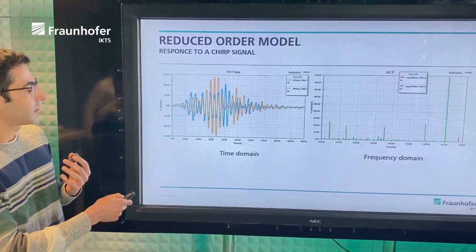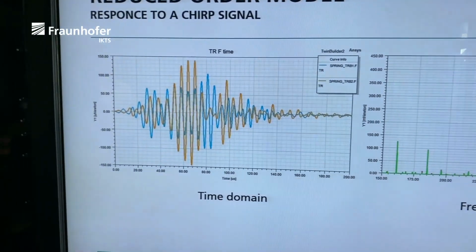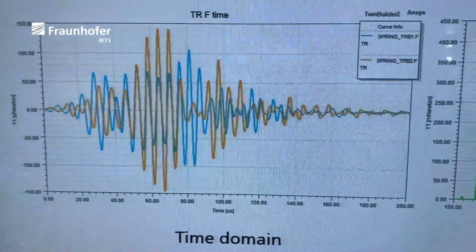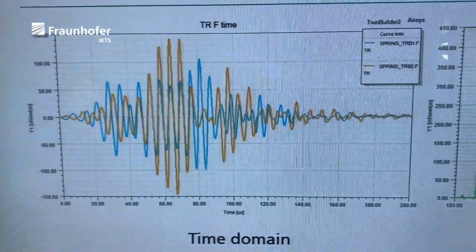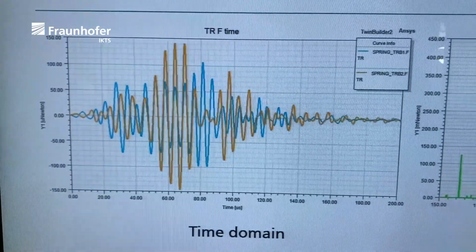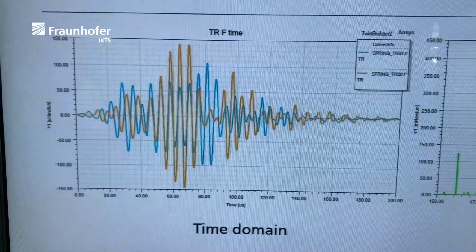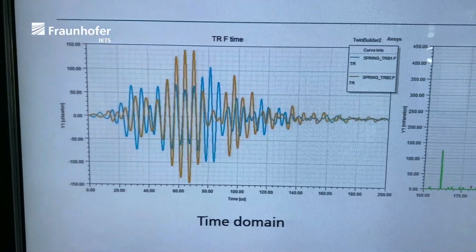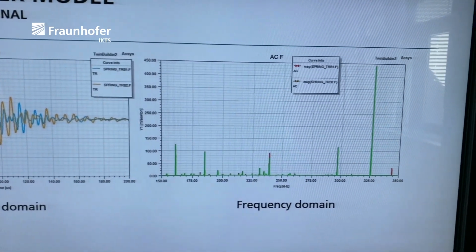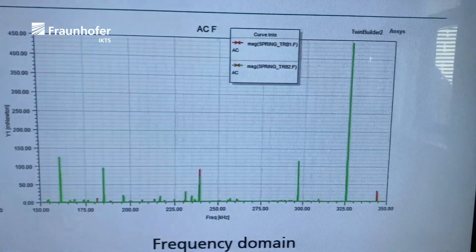Let's look at this. In our model, we are able to send any kind of ultrasound signal through our sender, and our model shows the response from those two receivers. One of the lines shows receiver 1, and another line shows receiver 2's timed response to the signal. To the right-hand side, we can see the frequency domain response, which means we are able to see the response to any kind of frequencies coming from the sender.